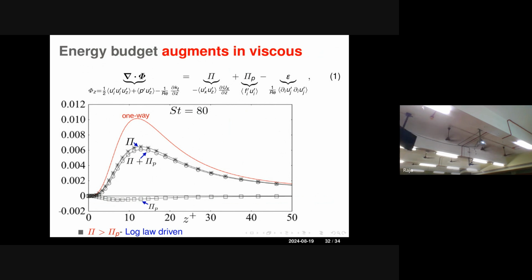So this is the complete balance of the terms, the Reynolds stresses. What kind of fluctuation energy extraction happens, the production term, what is happening in the system, the particle-driven source of energy, to how much is really dissipated out. That entire summation is what we are showing as a function of wall number properties.